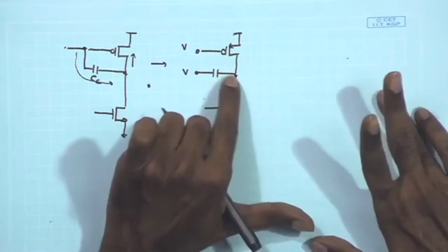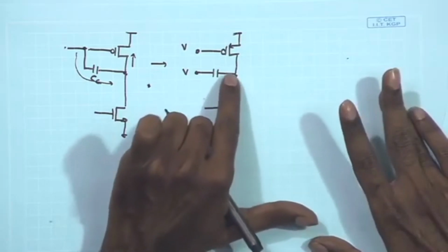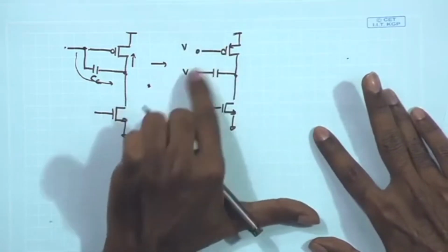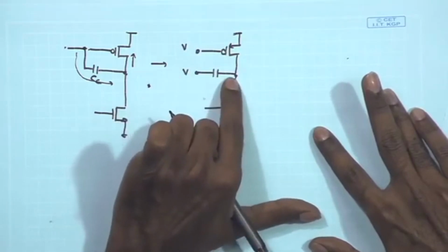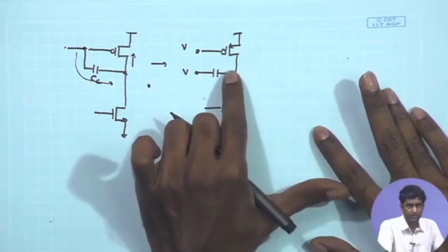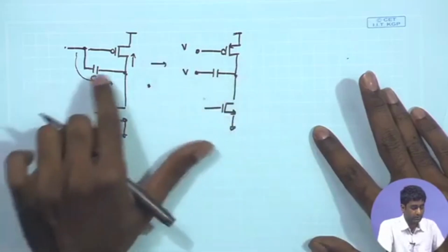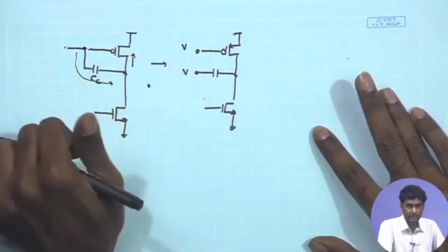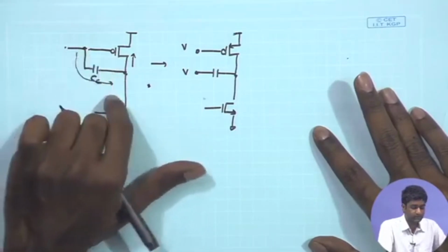At a particular frequency, if they cancel each other, then you have a zero, because the overall small signal from the inverting and non-inverting paths will be 0, and that gives us the frequency of the zero in this circuit. So far we have ignored the zeros, and that happens because we are taking approximate analysis. We are assuming the Miller effect and breaking down the capacitance at different nodes.